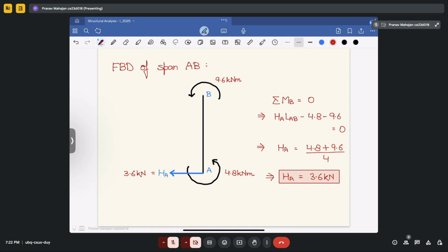How did we do it? We used a compatibility equation at the center of the beam, and then determined all the slope deflection equations and utilized the compatibility equation. We first determined the value of slope, or rotation, at the support at the center, and substituting the value of the unknown in the given equations of the end moments, we determined the absolute moments in the beam.